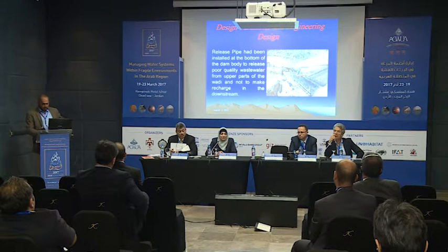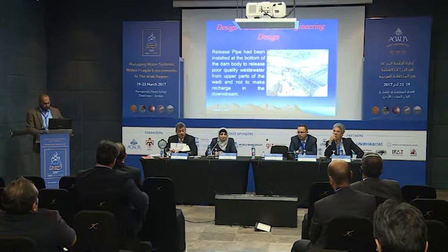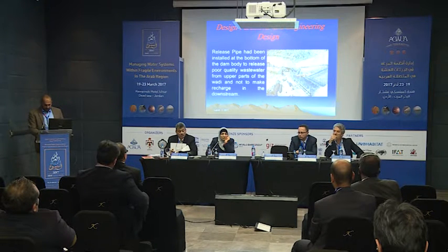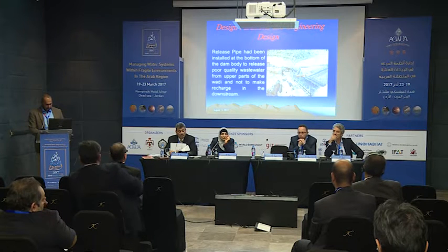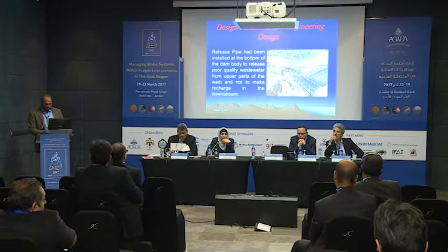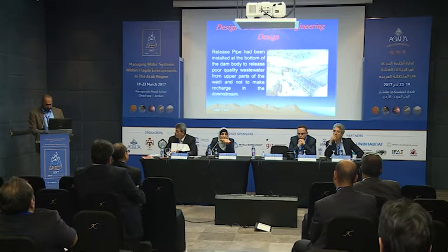We have also a release pipe that has been installed at the bottom of the dam body to release poor quality wastewater from upper parts of the wadi. These pipes are definitely not to make any recharge in the downstream. It's just to release the wastewater from the upper parts.